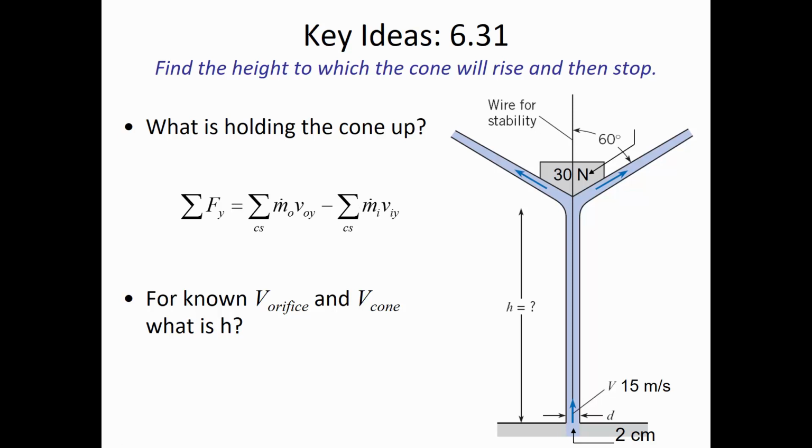And so then you'll know the velocity here, and you know the velocity there. And actually, Bernoulli's equation can tell you how the velocity changes as a function of elevation. Because this is a jet of water, the pressure here at the opening is 0, and the pressure up above at 2 is 0.